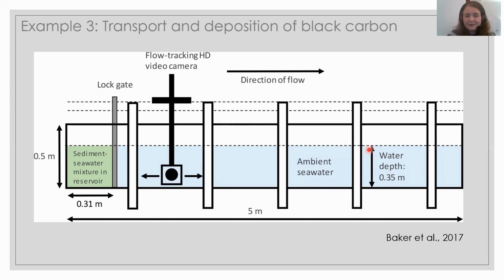And for these kinds of preliminary tests of what you could do, I have used one of the 2D flumes. I only did this experiment at the end of October, so I haven't even drawn up my own sketch of it yet. So I'm using a sketch of Mac Baker here, but this whole setup is basically the same. The only difference is that I used a false floor that's spanning from the inlet box up to 4.5 meters into this tank that is 5 meters long altogether.